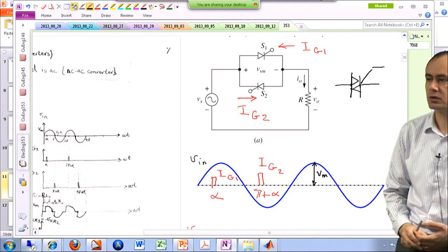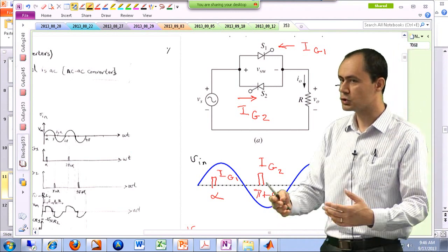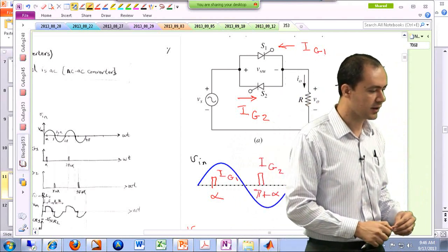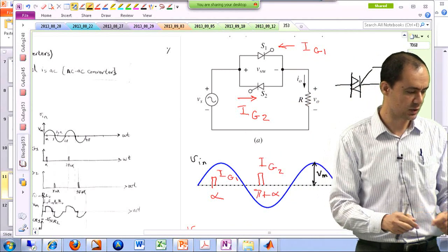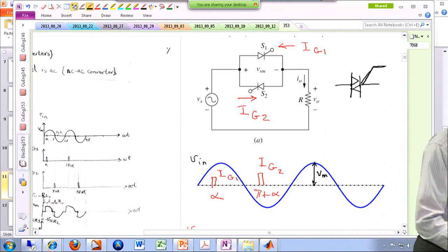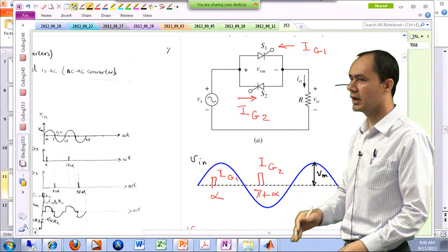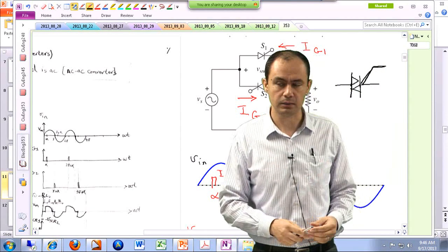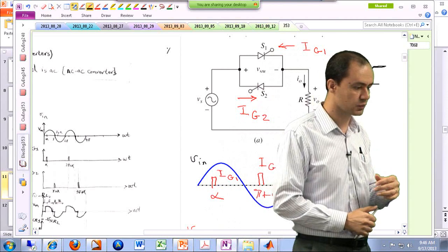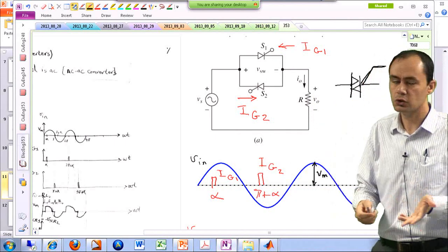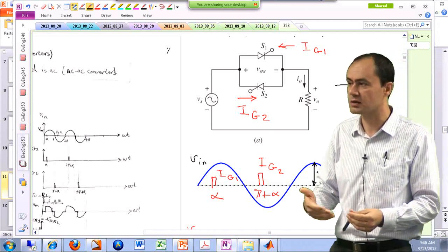Like this, which is called a Triac. So it's basically two SCRs back to back in parallel with each other. And then their gates, so this is the gate for both of them. You can trigger this gate when the input voltage is positive. This will be only applicable to SCR number 1, and when the input voltage is negative, it's applicable to SCR number 2. But you don't hurt an SCR if it is reverse biased and you trigger it.